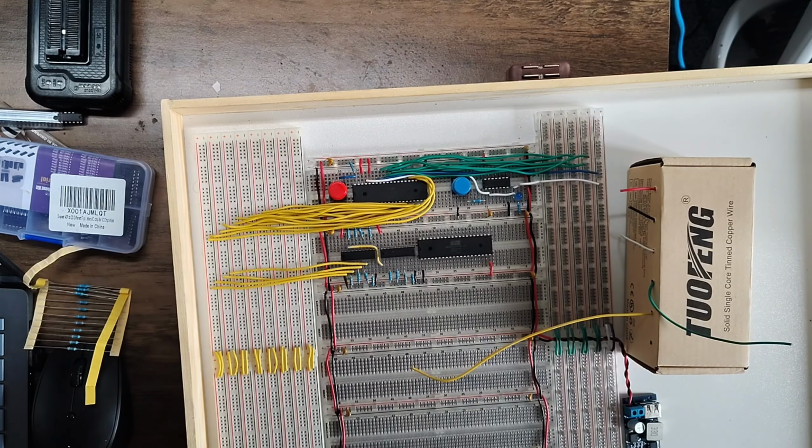And what that will do is, if the first chip meets the criteria, it will then enable the second chip, and then we can check if the second chip meets the criteria, and then the output of the second chip will go onto our 65C22 versatile interface adapter, and then that will work. So I will get the address lines installed, and then we will look at the next section.